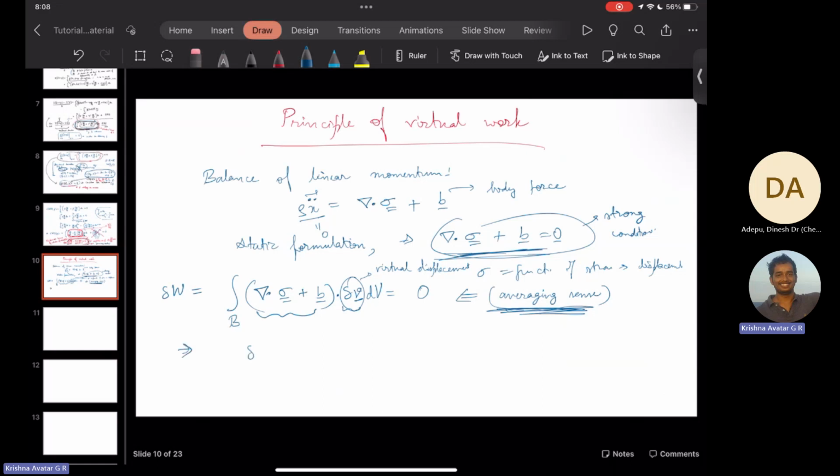And this we can write as W as a function of the X vector. In these entire notes, I have not seen how they have defined the expression for displacement, so I'm just using X itself. This expression can be written like this; these are equivalent expressions. We see clearly that the variation of W at the X vector gives the state of deformation for minimum potential energy along any direction delta V vector is zero. So this is the principle of virtual work.